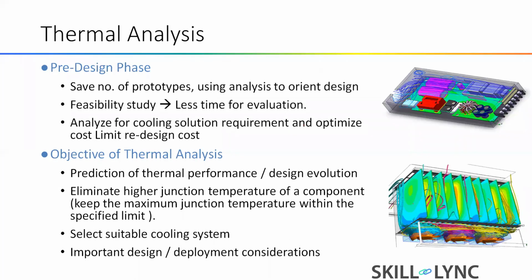Now we understood how important thermal analysis is, and in the design process we have to include this thermal analysis in the pre-design phase itself, because if we include thermal analysis after all the design phases are over, like electronics and electrical design is over, PCB design is over, and then at last we do thermal analysis, we will have very limited scope to change the design.